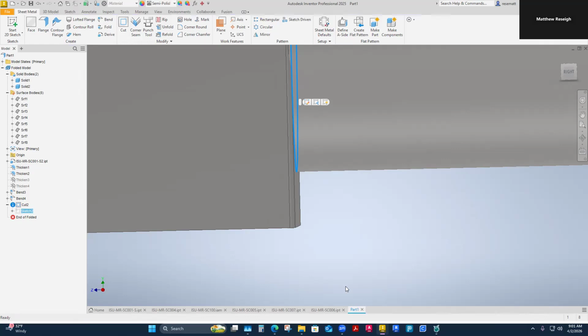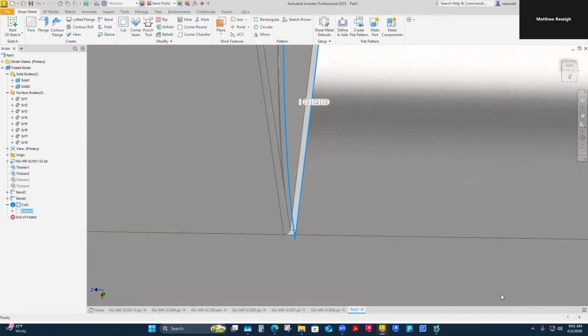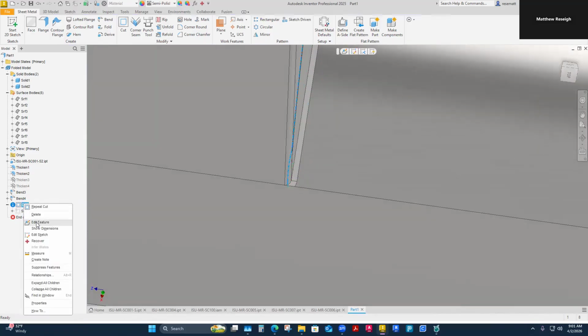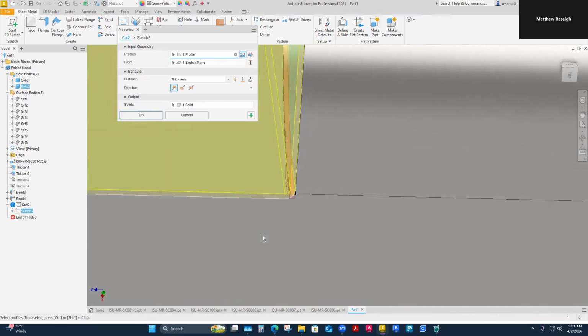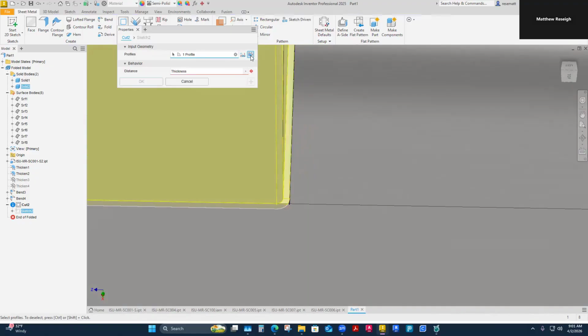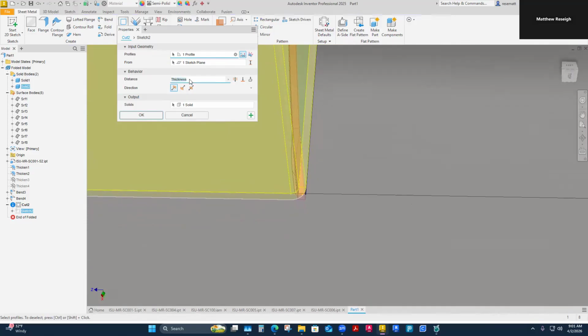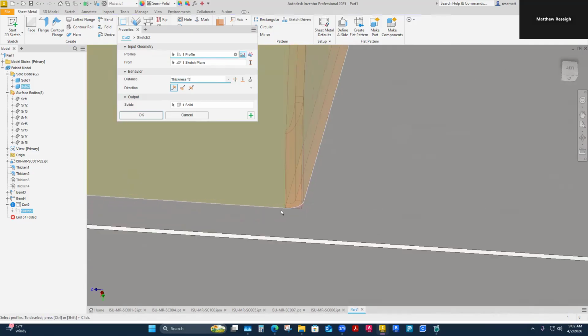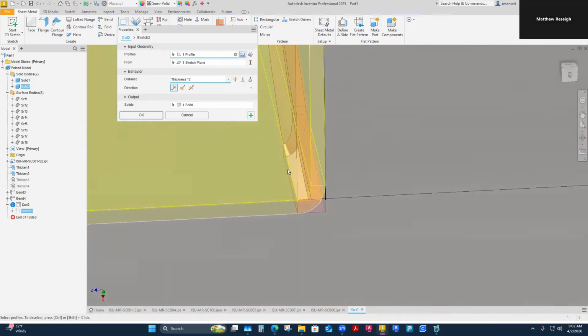Well, that's what I'm going to look at here because I've moved it. Now what I'm going to try to do is cut beyond just a thickness. So I'm going to come in here and re-edit my feature. I think for one, I've got to go the other direction now. Then can I cut across bends here? Still not. I was hoping I could cut across bends there. And if you do a thickness times two, I don't know if it'll accept this. That definitely cuts through, visually it looks like. So all I've done is extend beyond, and it's almost like going to cut this through that bend a little further.